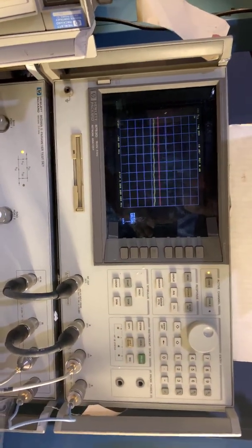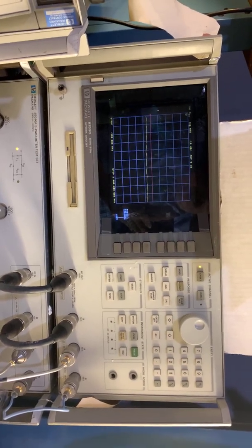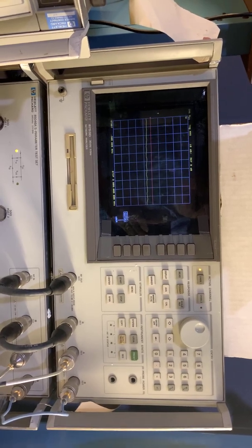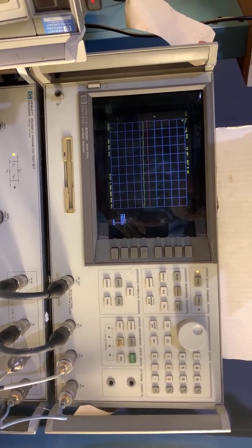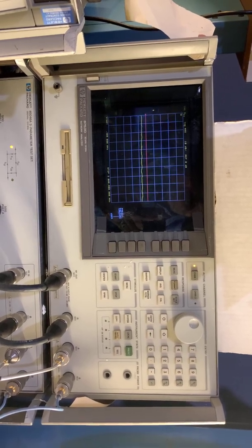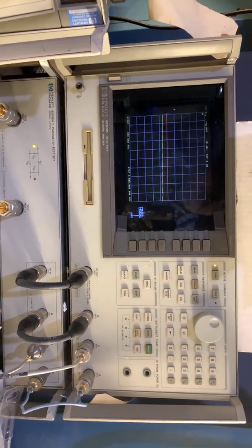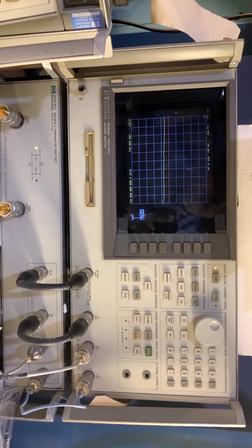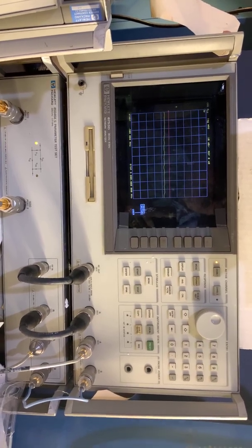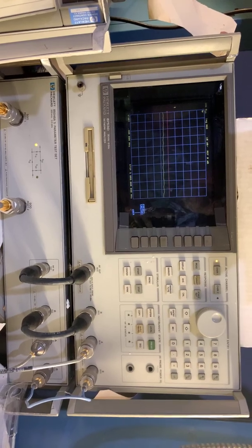The microwave analyzers usually start at 10 or 45 megahertz, but can cover frequencies up to 50 gigahertz, newer models 67 gigahertz, or even 100 gigahertz, and then using external frequency extenders, they can cover all the way up into the terahertz range. But it's a pretty expensive game up there.